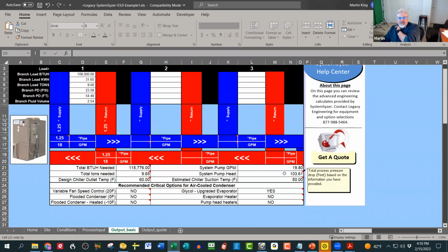See what it did to the head? It jacked the head up because of specific gravity and viscosity, the delta P. And it'll also recalculate your feet of head based on the viscosity if you drop your set point. So because it gets colder, it's getting thicker, right?